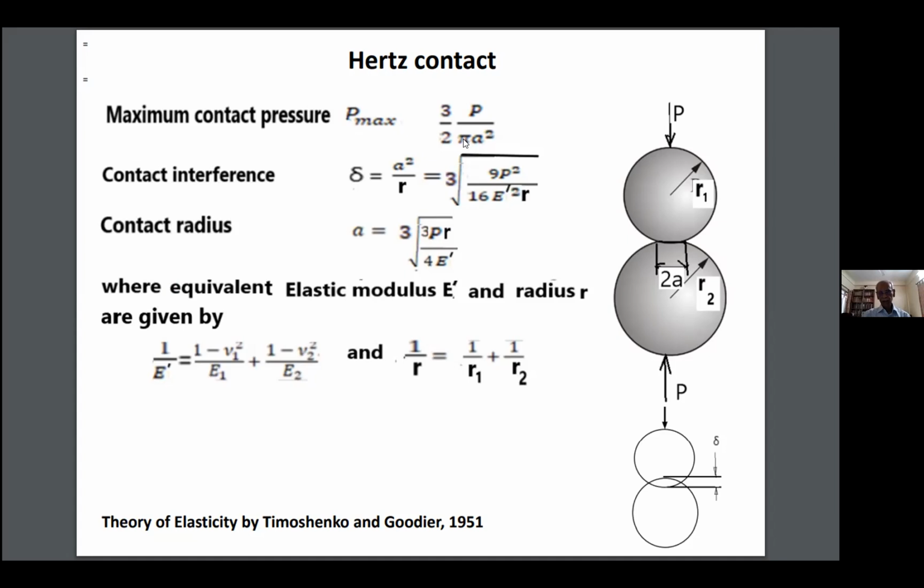In fact, the contact pressure is semi-elliptical in nature. I'm not going into the details of this. The peak pressure at the contact is given by 3/2 P by pi a square.